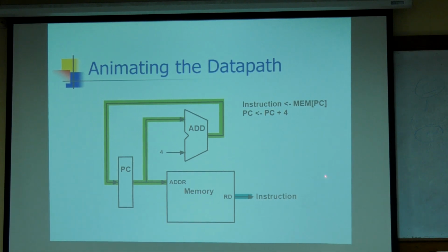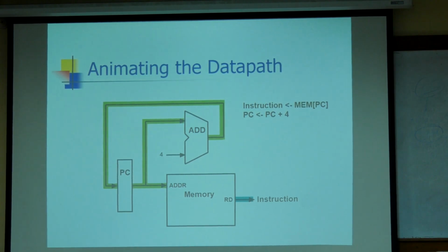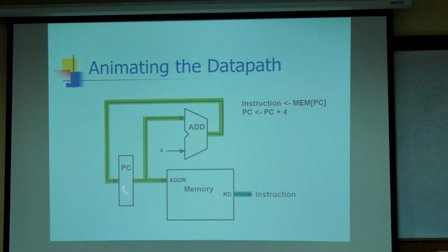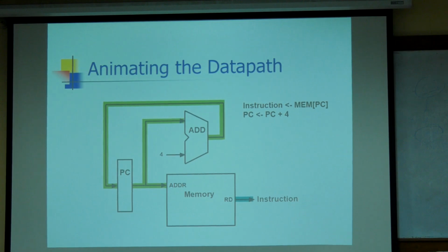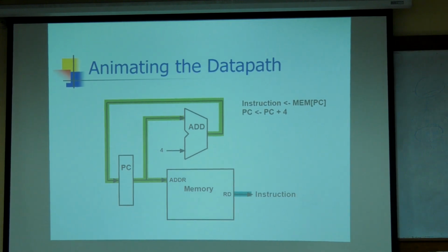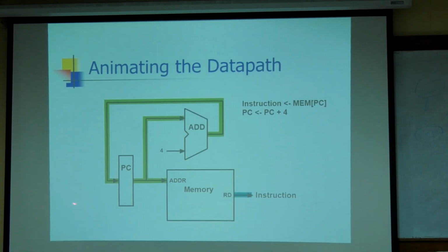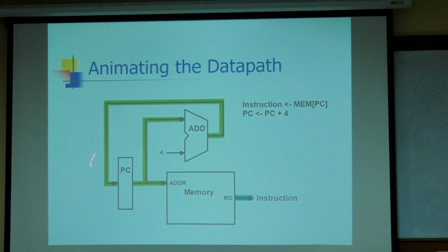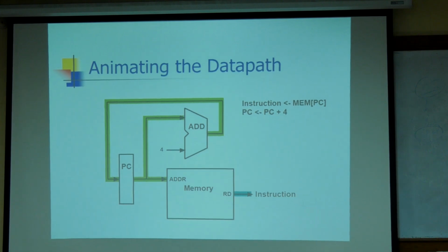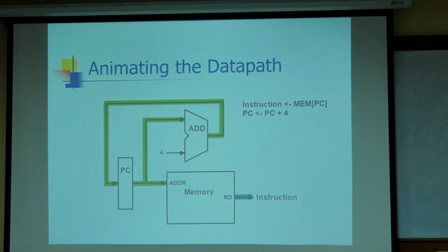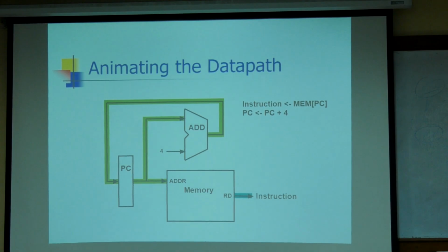In this fashion the program counter performs the incrementing operation. Here we have not designed a counter. PC here is only a register, just holding and writing the data. We implemented PC as a register, and PC plus this adder together becomes a counter.